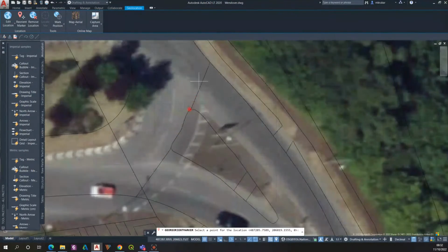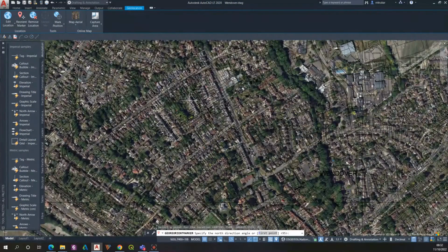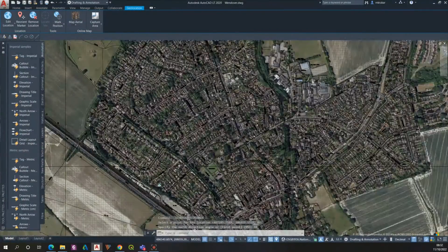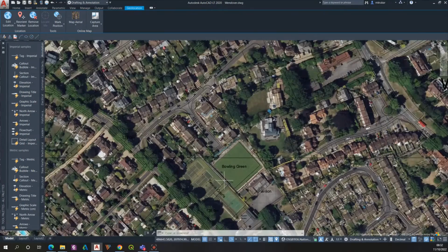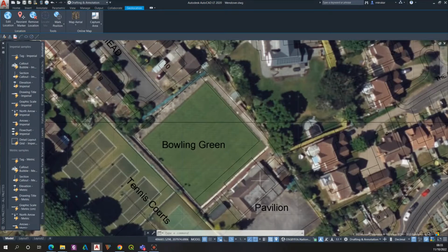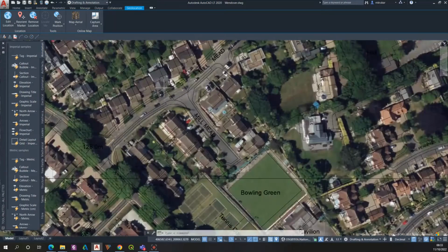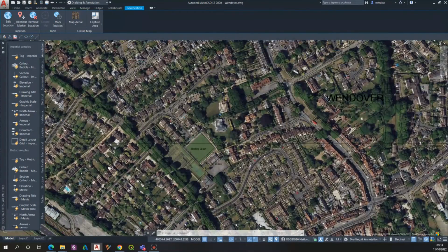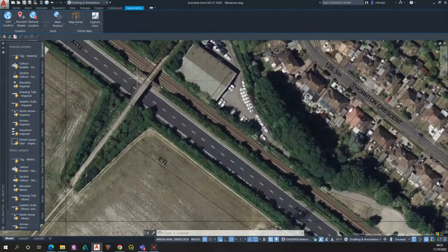So let's go back to the beginning and try 91. 91 seems to be quite correct, almost correct. As you can see, this tennis court doesn't cover the AutoCAD drawing, so I think now is the time for changing the point location. But before I do it, let me check that everything is alright with the north direction. Seems like it's quite fine by now.